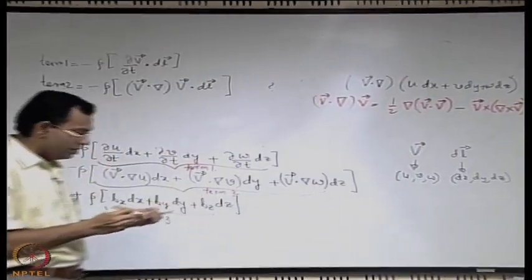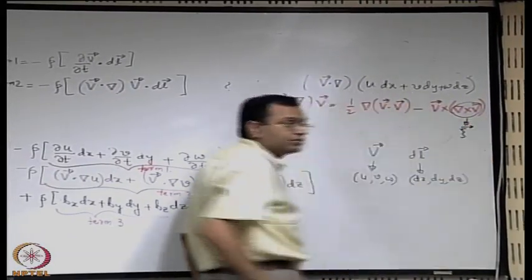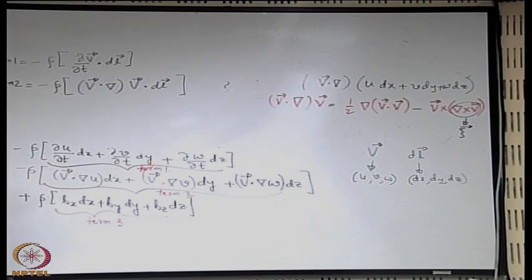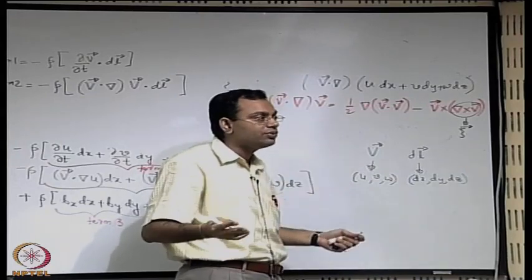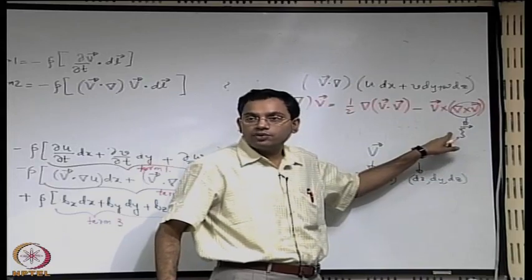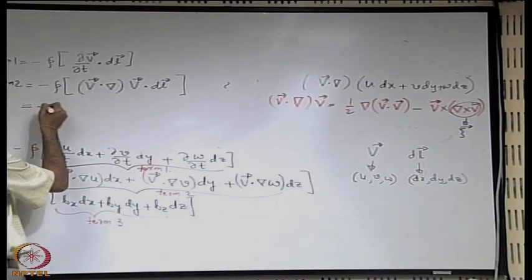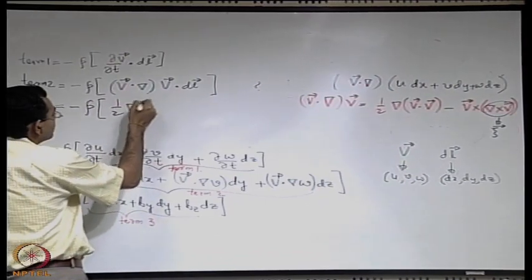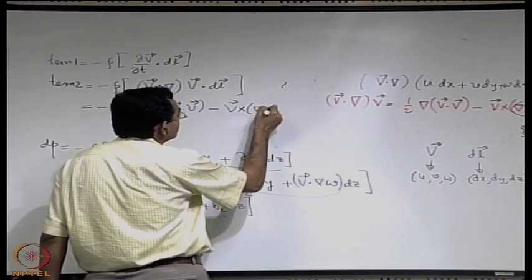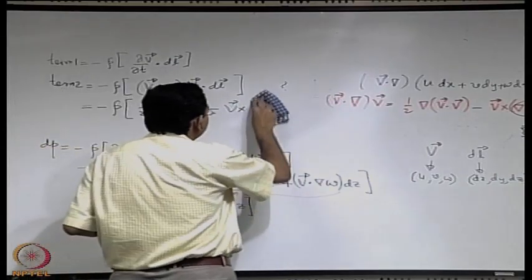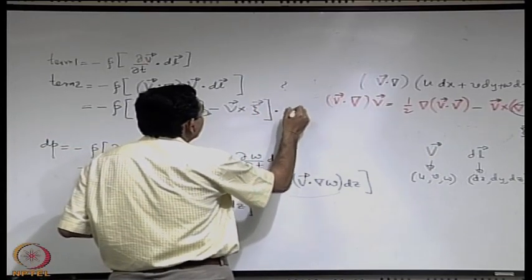Now, why we are putting it in this particular form is because here you get the vorticity vector, and we were finding out that the condition of rotationality or irrotationality has some influence on the pressure difference between the points, and this vector solely is responsible for whether it is rotational or irrotational. Okay, so we will put that simplification here, we will put this as minus rho half, in place of the curl of the velocity vector we will write the vorticity, then dot dl.